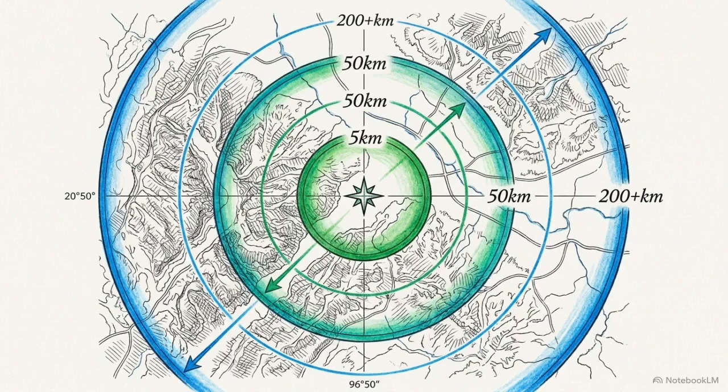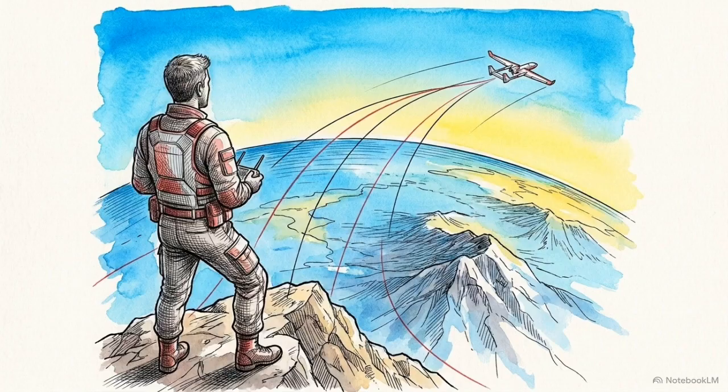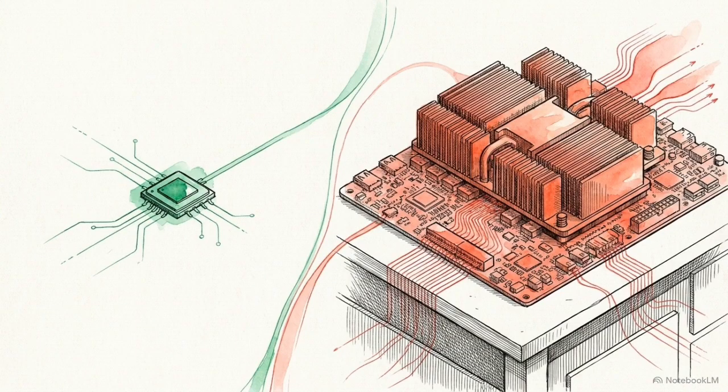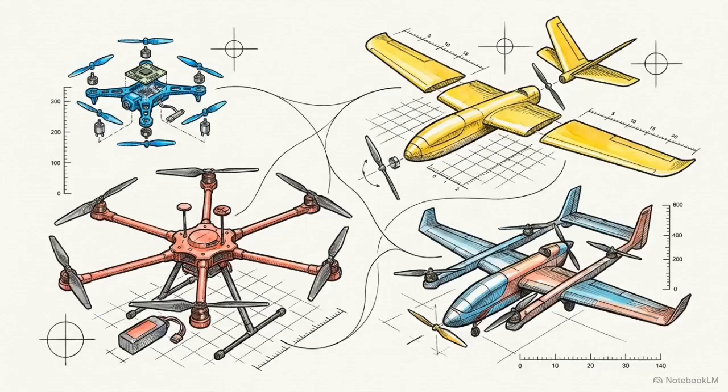These levels of autonomy define the operational range. While medium-range flights typically reach 50 kilometers, specialized autonomous platforms can operate beyond visual line of sight at distances exceeding 200 kilometers. The physical mass of a drone restricts the size of the sensor and processor payload it can carry. This capacity directly limits the onboard computational power, which determines the maximum level of autonomy and operational range the platform can achieve. Every drone functions as a specialized configuration of morphology, avionics, mass, and software, precisely tuned to meet specific operational goals.